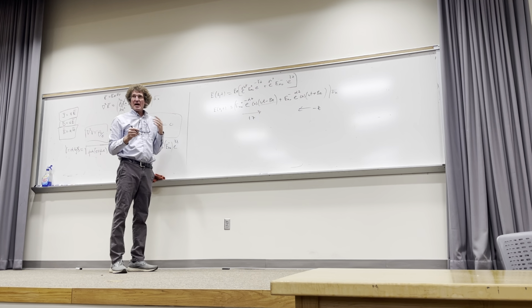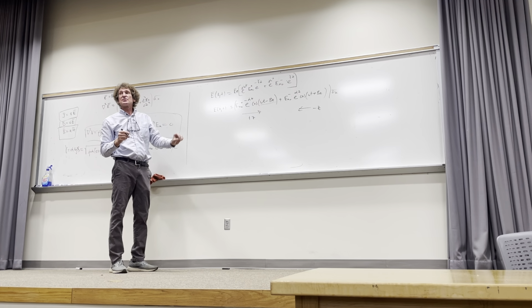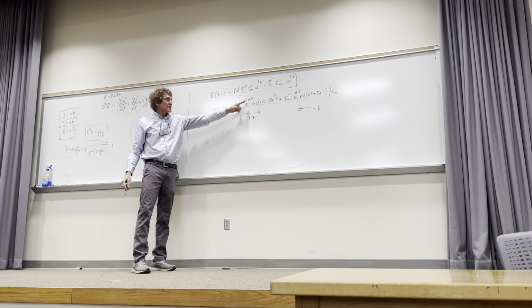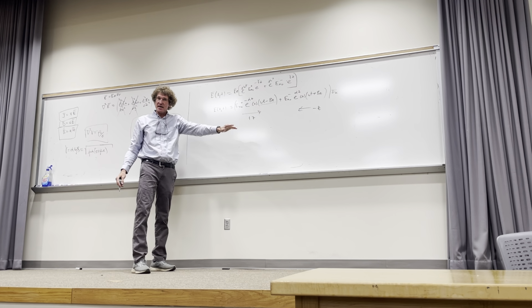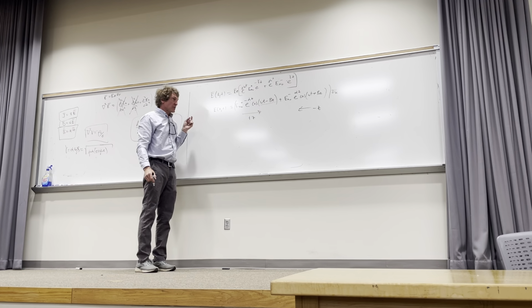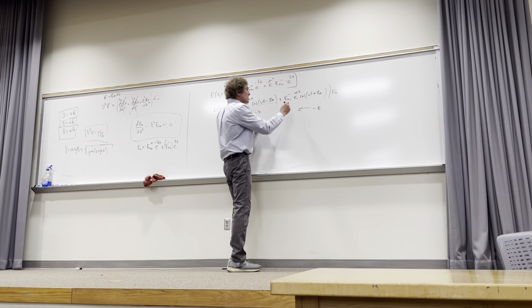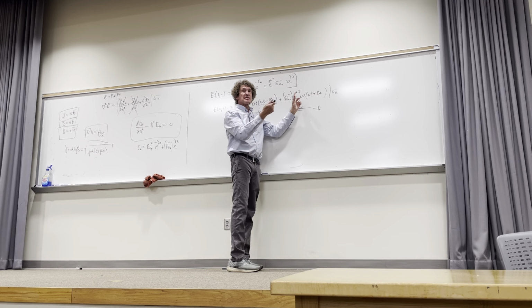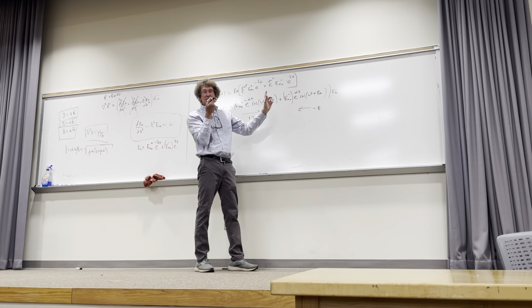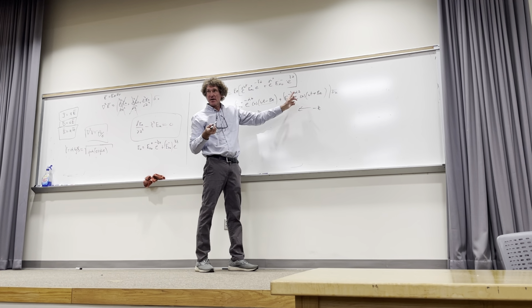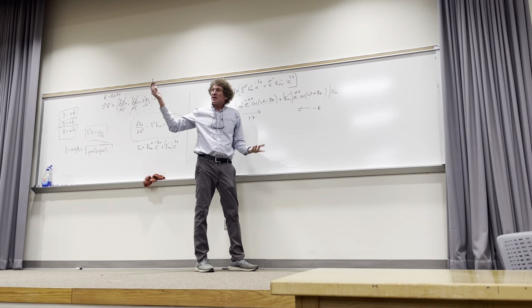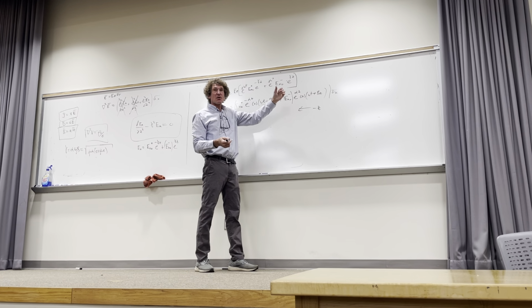Now, something that always happens is as the wave's moving, it loses amplitude if there's loss. You see that e to the minus alpha z there? As z gets larger and larger, this thing's decaying down to nothing. You all follow me on that? That's a wave going in the plus z direction. For this one, this is e to the alpha z, but it's going in the negative direction, right? Just think about this. As z gets negative, this will become smaller and smaller and smaller. You all follow me? It's basically, if it's going in the other direction, this thing will start attenuating.